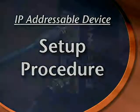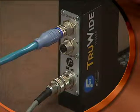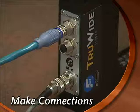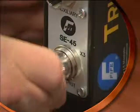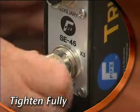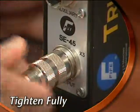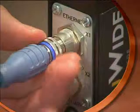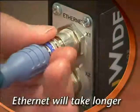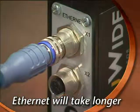First, install the sensor by connecting the SE45 analog connector and then the Ethernet connector. Note, it's important to thread each connector all the way until it's tight, or your sensor may not operate properly. The Ethernet connector has more thread and will take longer to connect than the SE45 connector.